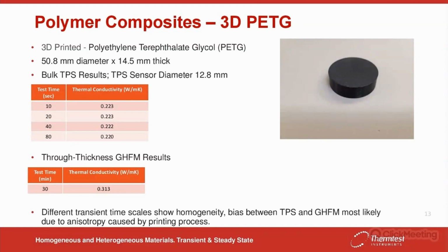And that has merit, and it does improve your results, but ultimately you have introduced error that is not defined because of that. Again, when your time scales change, your thermal conductivity changes, you have now introduced error to your ideal theory. And the larger the change in time scales and thermal conductivity, the greater the degree of error.